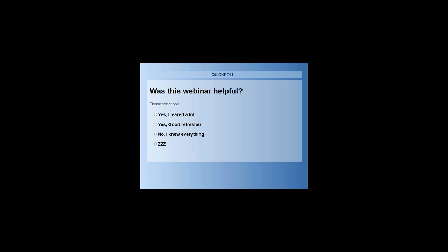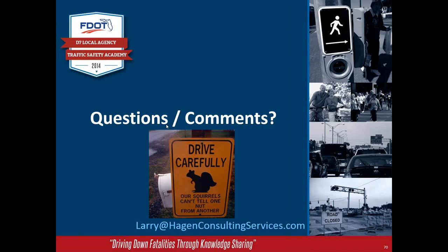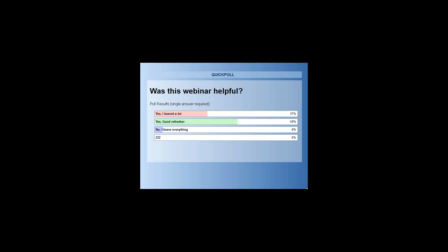So the real way to reduce rear-end crashes is to do some really active speed control, so people are going roughly the same speed. Because if you've got somebody going a little faster coming up on a person going a little slower, and the guy in front hits the brake at the same time the guy in back hits the gas, then a rear-end collision is unavoidable.